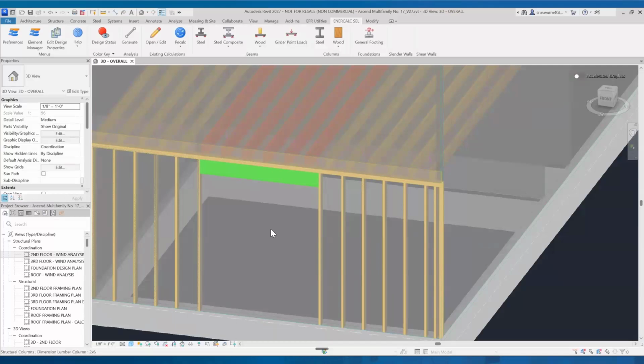The other girder-like header example that we're going to touch on is over here in the stud wall area. The thing that makes a stud just subtly different from a column that we just looked at a moment ago is mainly that your bracing conditions are going to be drastically different about the two axes. Typically, if you're inside a wall, then you're going to be sheathed in one direction, and your column will essentially be fully braced in the weak axis and typically fully unbraced in the strong axis. And so we're going to go ahead and go through the process.